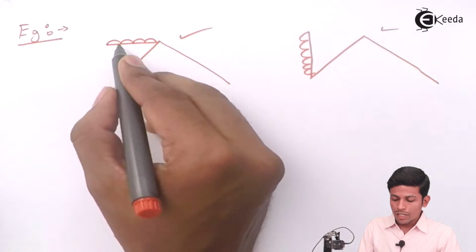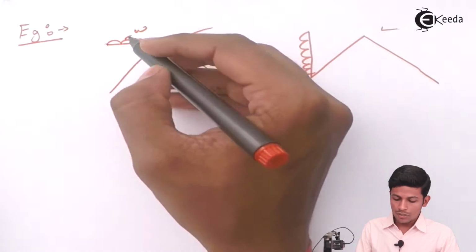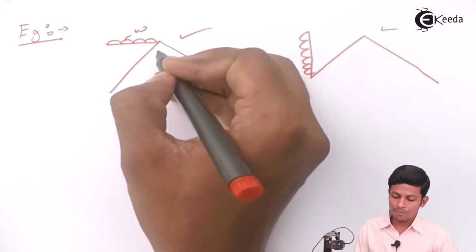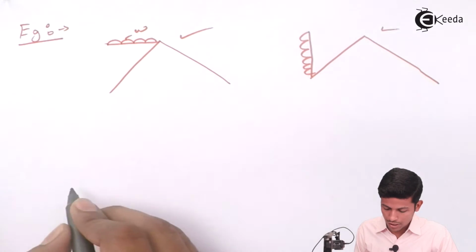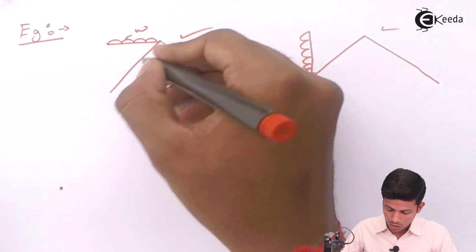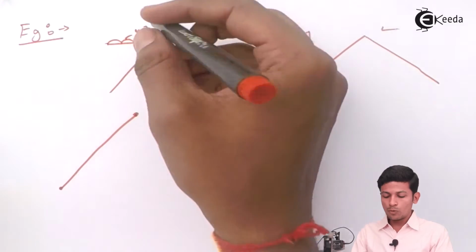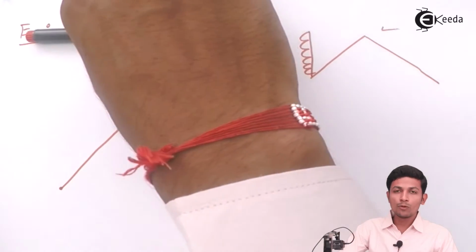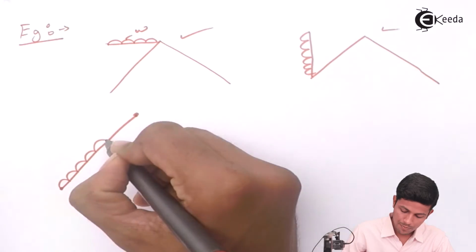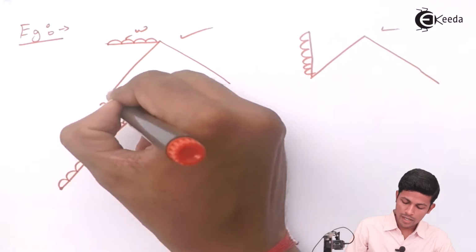For example, let's solve this first one. This UDL W we have to rearrange on this beam. How will you arrange it? There is a certain formula given for it. Draw the FBD of that part. Simply this W is rotated and put on this beam like this, and the formula will be W cos square theta.